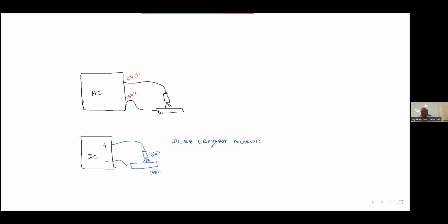So, we will go for this type of equipment where you want to melt the electrode, because the electrode will have 2/3 of the heat. Which processes are melting the electrode? SMAW, except GTAW, SAW, GMAW, FCAW. These processes generally we will go for this. There are exceptions, but forget about the exceptions. This is the rule.